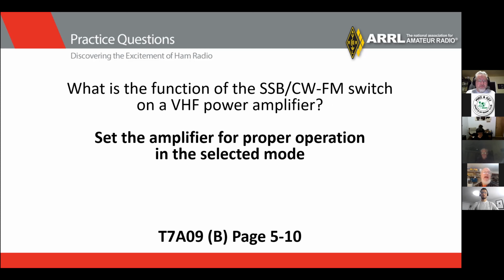So therefore, they can actually put more power on the CW and FM side than they would on the sideband. If they got like an 80-watt linear, you'll go 80 watts on CW and FM, but you may only be doing 60 watts on the SSB side because it has to be a real clean signal to send the audio across.